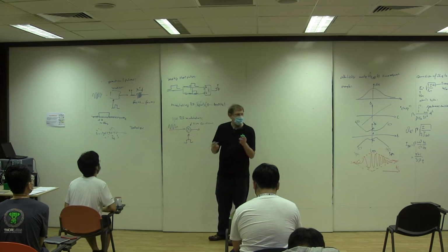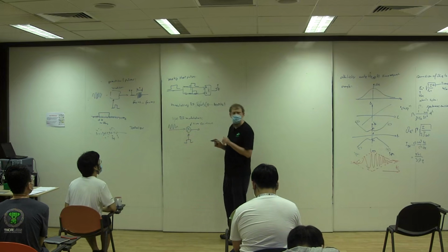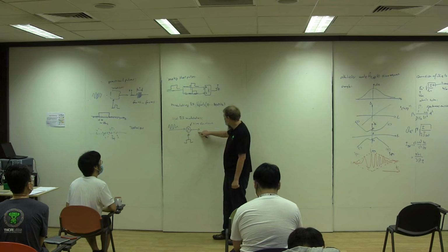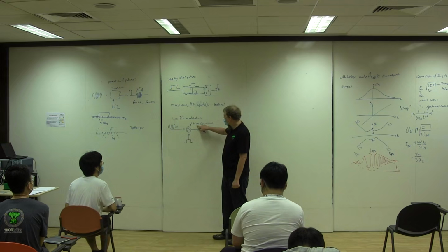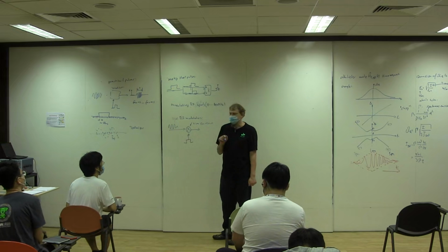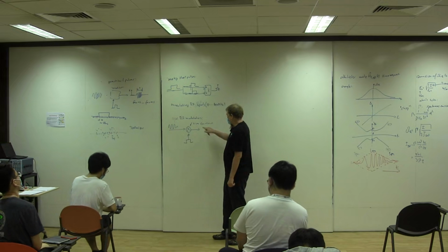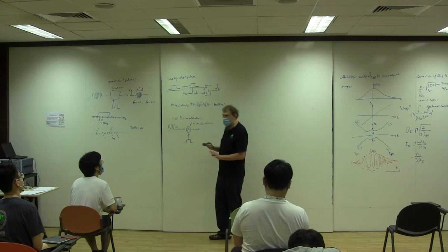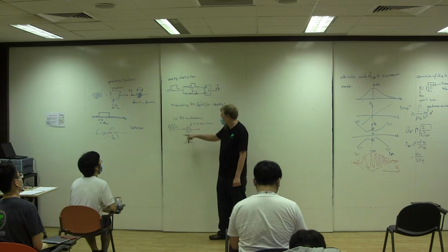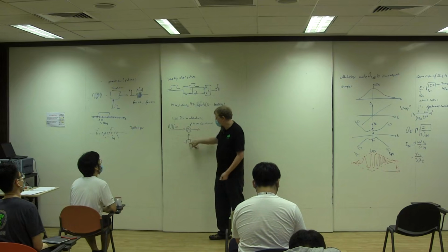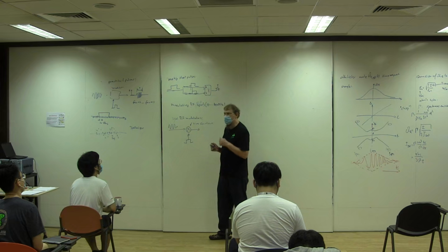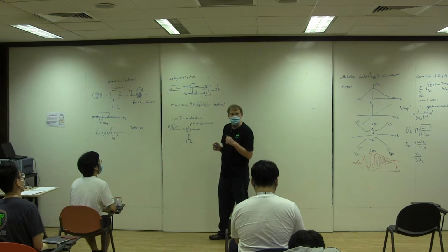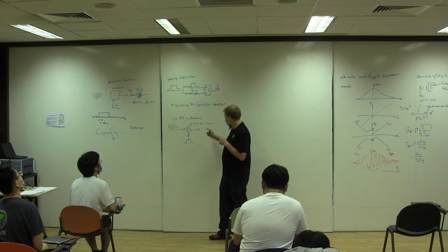We saw this in the homodyne or heterodyne, I hope. Oh, maybe we didn't see it. I forgot whether we covered this. A radio frequency mixer makes for a nice modulator. Some are better than others, so you need to maybe play around with it. But if you need to quickly find some way of modulating a particular radio frequency with a given envelope, try a mixer. And if things go right, I could just show you how this typically works.